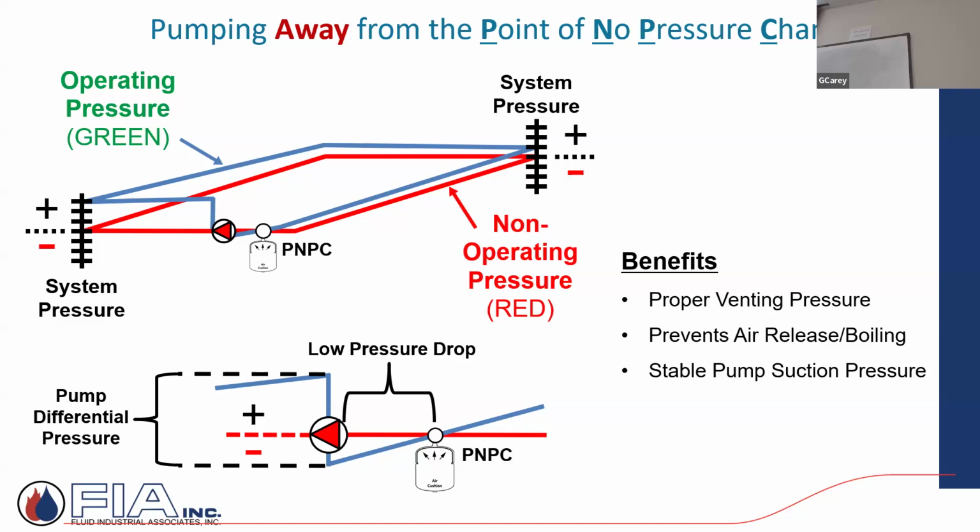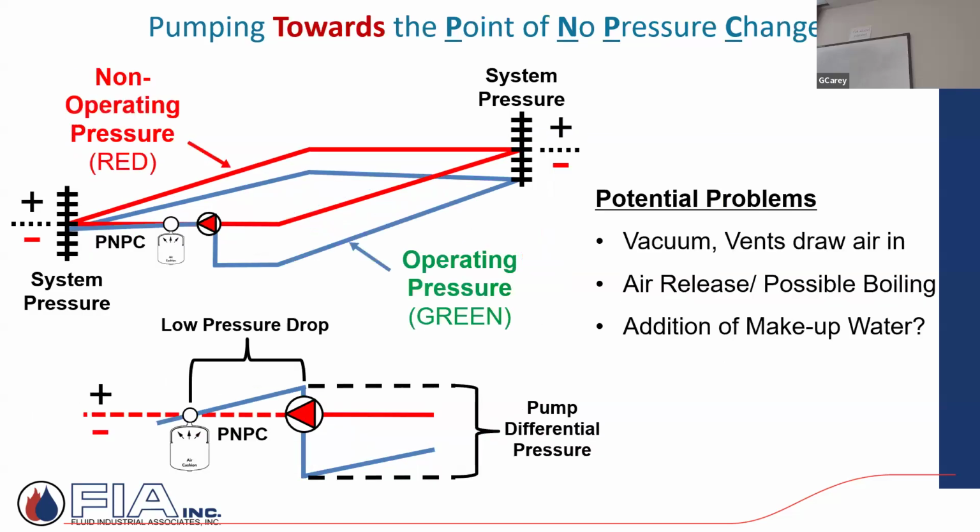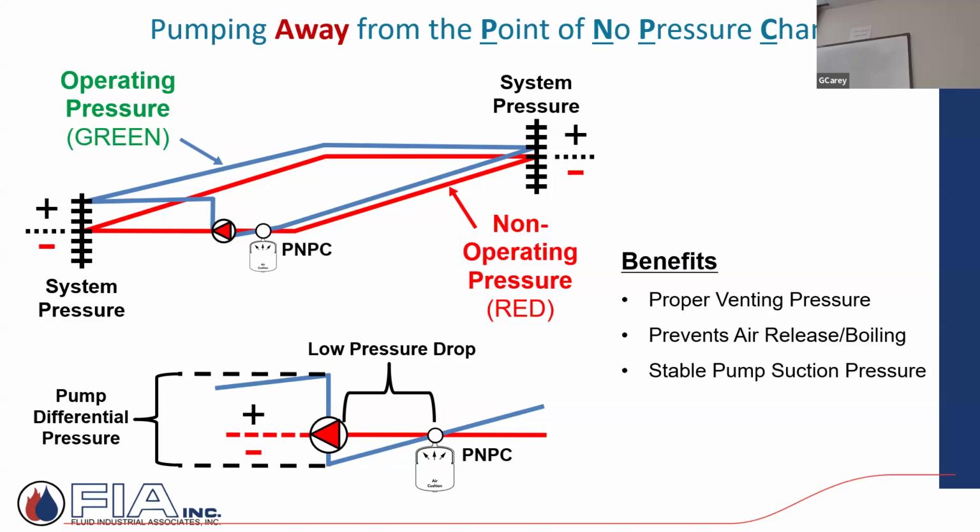So in a closed loop, you'll sometimes hear a different expression, but the pump in a closed loop system is a pressure differential machine. It just creates a difference in pressure. So if I put it in the wrong place like this, and we determined that we needed 50 feet of head, for argument's sake, and in this orientation, with gauges on the suction and the discharge and here's my expansion tank, that 50 feet divided by 2.31, call it 22 pounds, whatever the number is, would be additive. And then that 22 would slowly be dissipated down to 0. Not 0 pounds gauge, but 0 pressure differential, 50 feet.